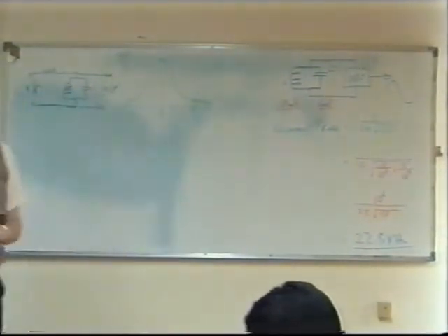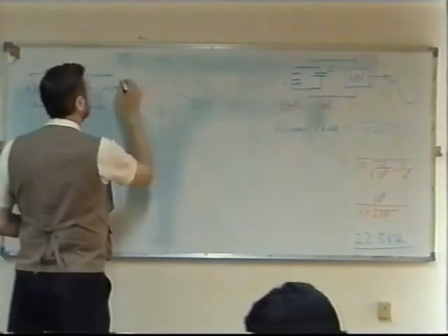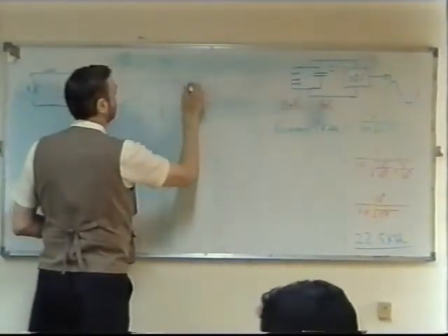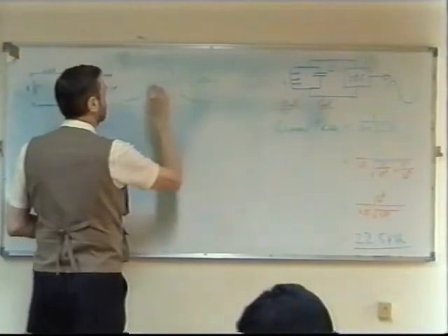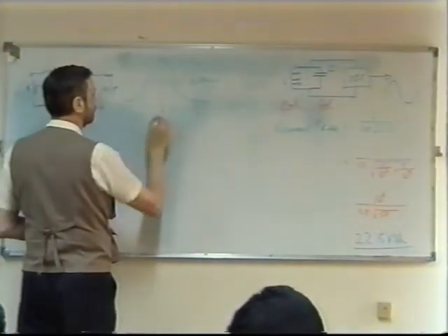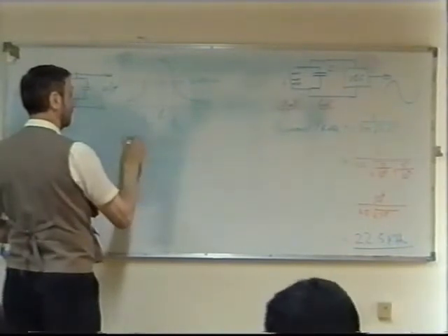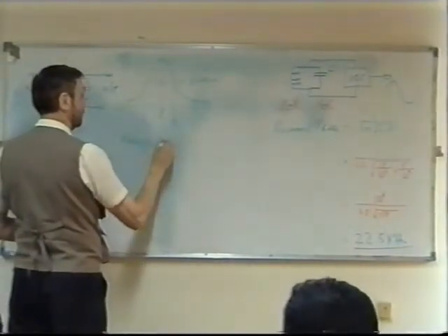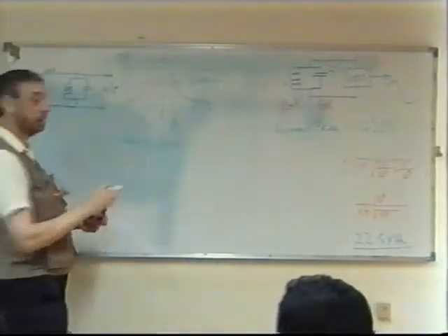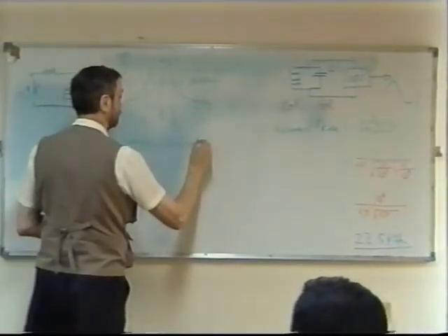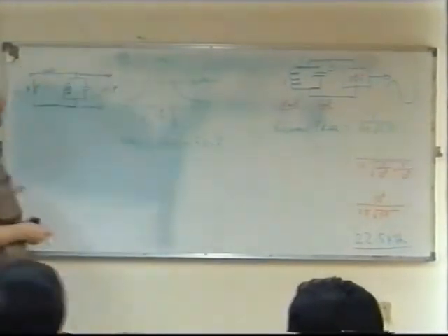And if we were going to measure our output as power, then at the half power point we had two frequencies. We'll call that F1 and F2. The bandwidth of the circuit is really the difference between these two, isn't it? Yes. F2, I should say, minus F1, the way I've drawn it here. That would be the bandwidth of the tuned circuit. Now, yesterday I didn't give you any formula to calculate that bandwidth, did I?